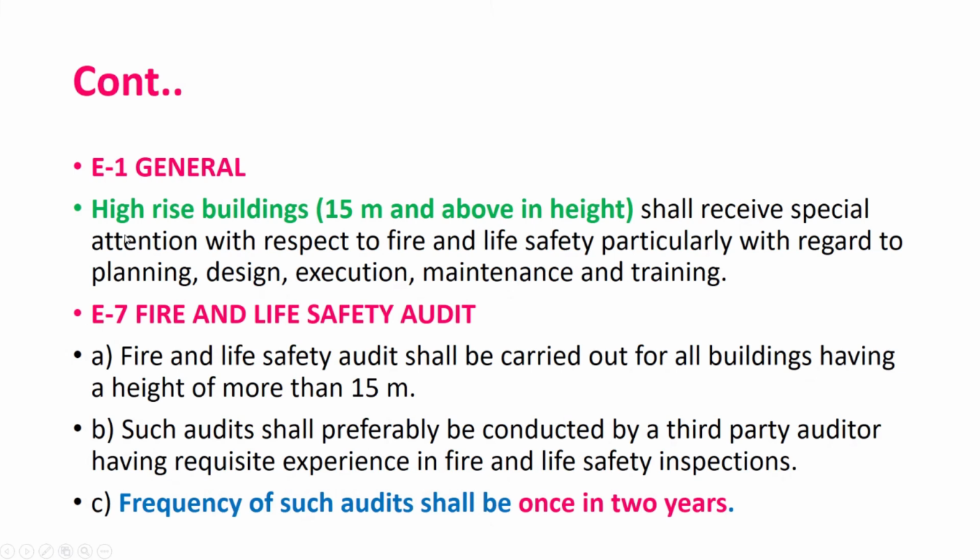Okay. So this I suppose is known to everybody. So 6 meters width I need to give as clear open space for the fire tender to move around the building. And mind well, the surface on which the fire tender is supposed to move, you must just try to relate it. Suppose you go into a big society, a high-rise building having maybe around 200 flats. In that case, you must have seen there is a lot of open area in and around that particular building. And there is a hard concrete surface provided just like a road on and around the periphery of the building itself.